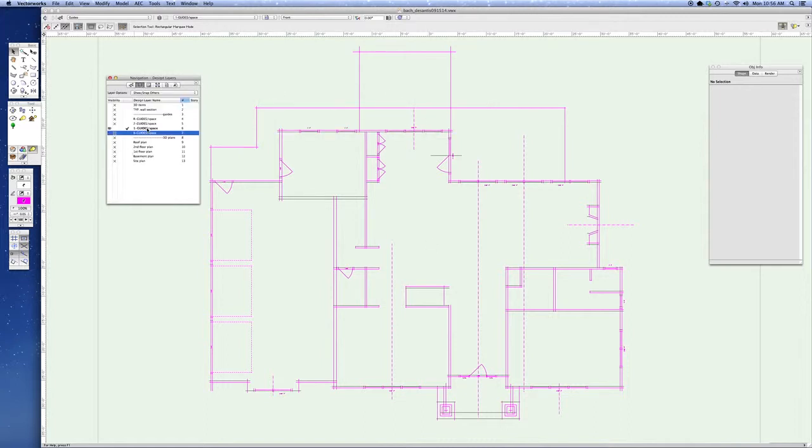for doing the layout. So when a job comes to you, it'll either already have all of these done and you can get right into the modeling process, or you'll have enough information to be able to produce this first phase of layout. The only other 2 layers on here are the typical wall section. That's just a layer where I keep all of my kind of boilerplate wall sections, those kinds of things. I'll talk more about that later. And then the 3D items,